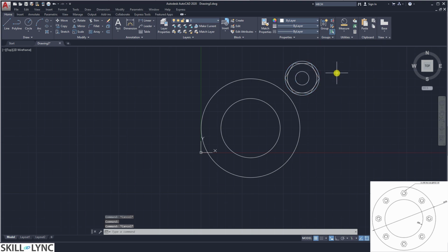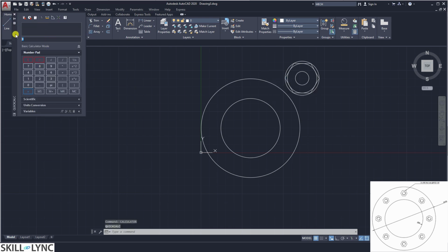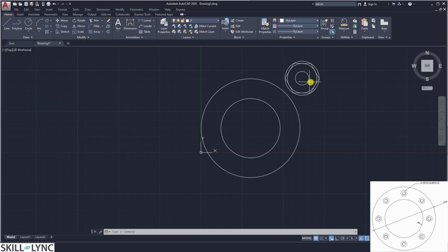And then we have drawn the nominal radius, but we'll draw the minimum radius. So typically the minimum radius is 0.85 times the nominal dia. So to quickly open up the calculator, let's see here, 0.85 times 8 mm of nominal dia will be 6.8. So the inner circle would typically be of dia 6.8. Okay, so let us draw this onto our model.